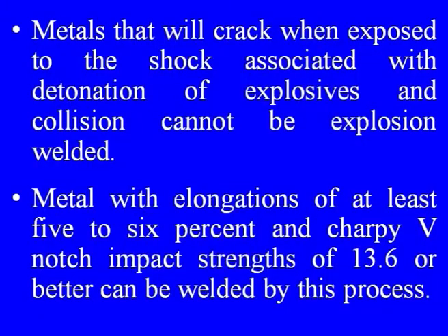Metals that will crack when exposed to the shock associated with the detonation of explosives and collision cannot be explosion welded. Metals with elongations of at least 5 to 6% and Charpy V notch impact strength of 13.6 or better can be welded by this process.